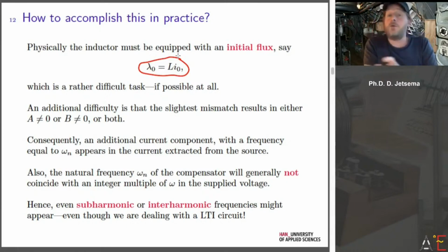That is of course what you want, because if you do power factor improvement, you do not want to put more dissipation in your system. You don't want to burn more energy than necessary, otherwise the whole approach doesn't make much sense. So you always want to design a filter with a very high quality factor, a very high Q, with as low an internal resistance as possible.